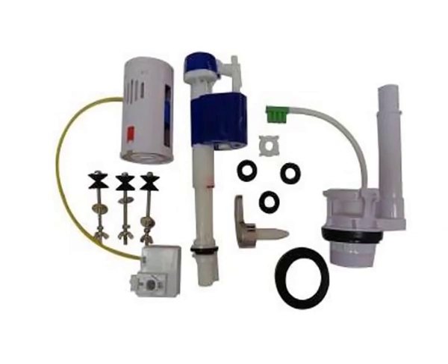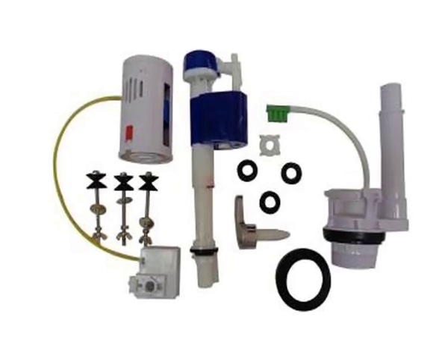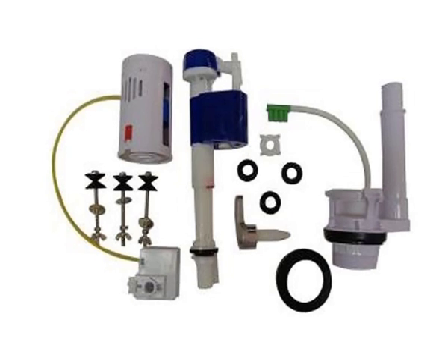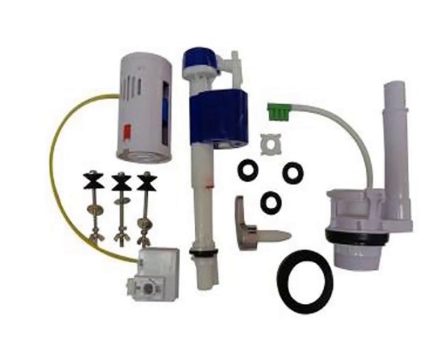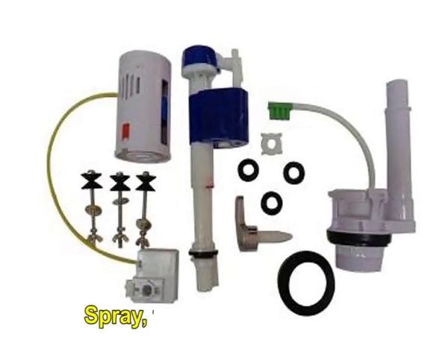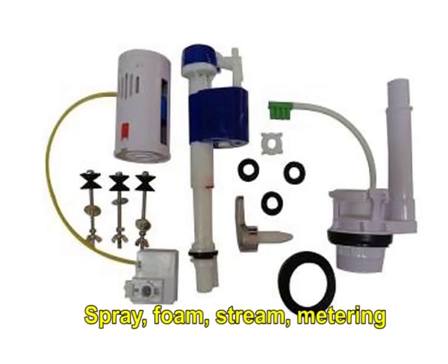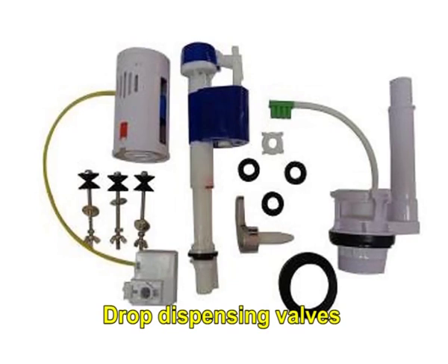This breaks up the product into small particles, giving a fine mist, coarse spray, foam, or dust according to the nature and relative quantity of the product and the propellant, and the type of valve, like spray, foam, stream, metering, and drops dispensing valves.